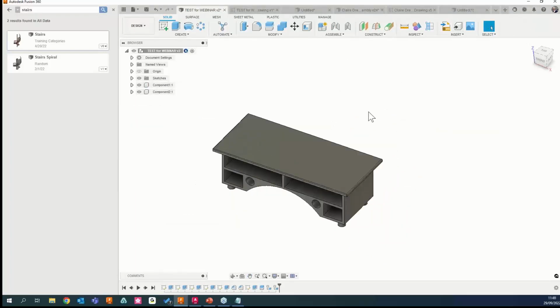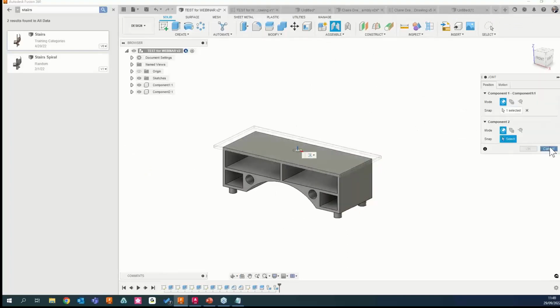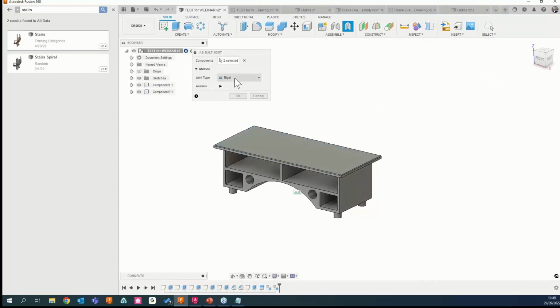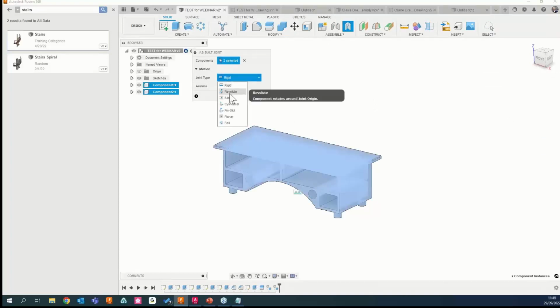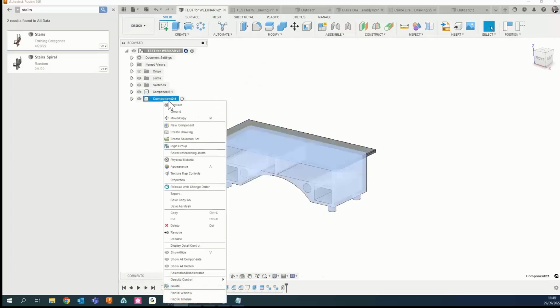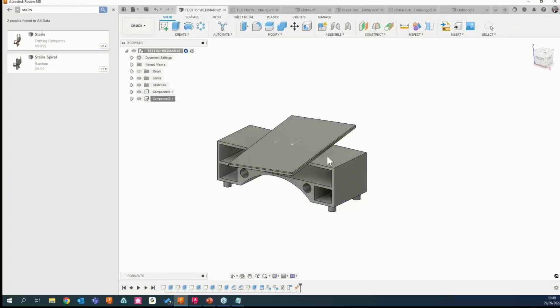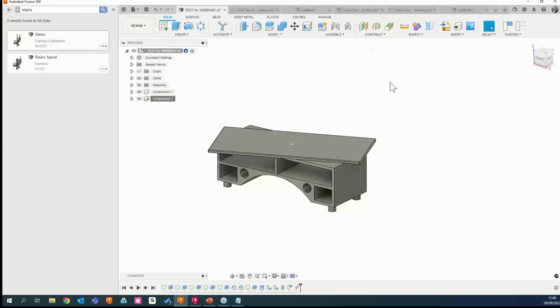We can stick joints on them to make sure that they don't come apart. We can put loads of different joints on them. Again, very simple. Let's say I want to do just for the crack, revolute around that guy, and then I've gone on this guy, capture position, and now you can see I can spin this around. Obviously, we're not going to get that spinning. I just wanted to show you something, because the rigid joint is what you've used there, but you can't do any motion with a rigid joint. It's just like you've super glued it into position. So if I go back to the bird box,